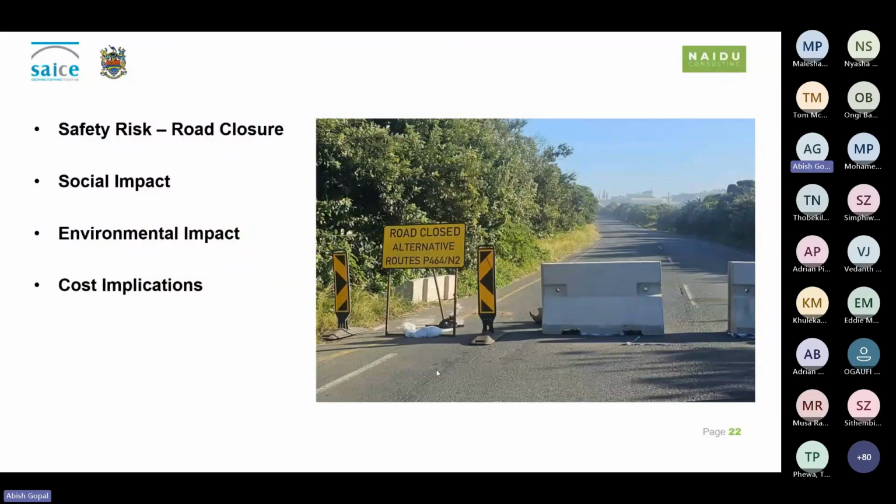Okay, so to start off with is the safety risk aspect. Based on the defects and potential movement, the bridge was closed to public vehicular traffic. Now, during construction, the safety of workers under the bridge was also a concern. Hence, as discussed previously, a temporary bracket was installed.